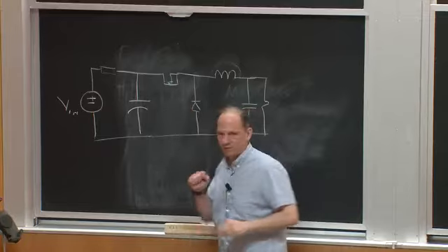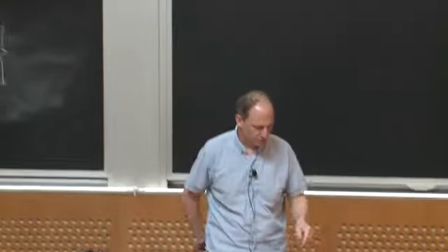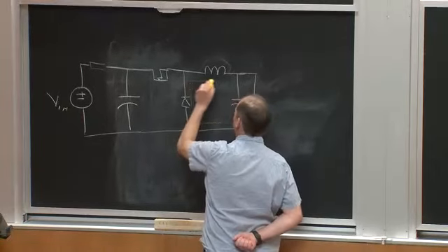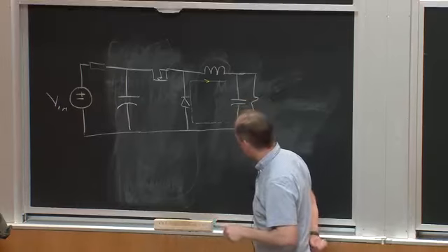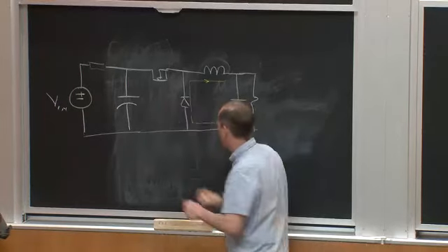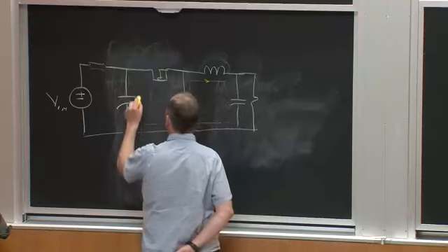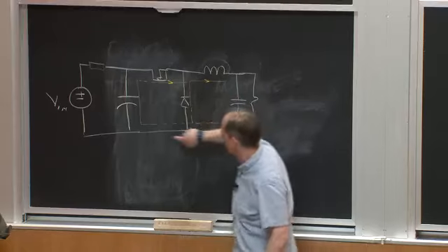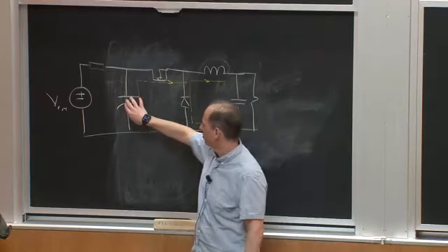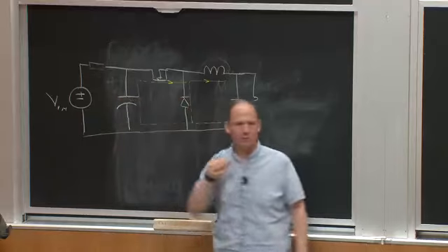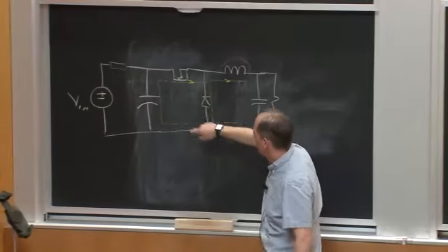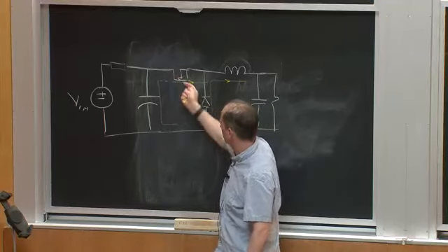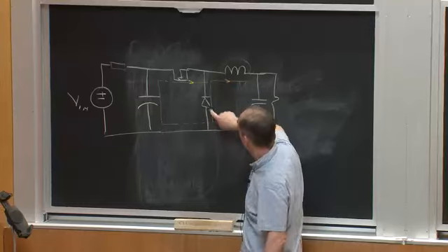As far as the switching of this circuit is concerned, when the diode is on, the path through the circuit is like this. When I turn the diode off and the switch turns on, essentially I'm commutating to this branch. So I have a commutation between this branch and this branch of the circuit, and I'm assuming all the high frequency currents go through the input capacitor, okay? Likewise, when the switch is on, I'm carrying current this way, and when I turn the switch off, from an AC perspective, I have a loop going this way.